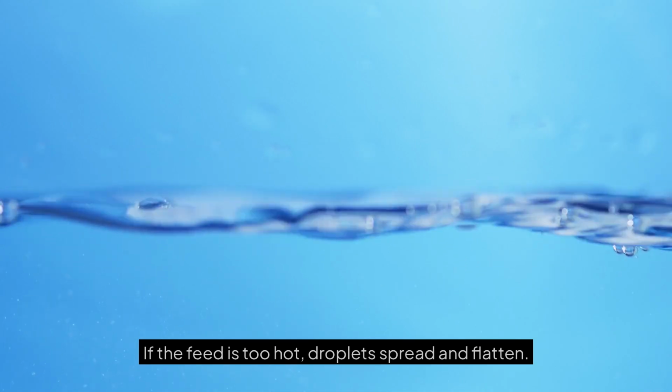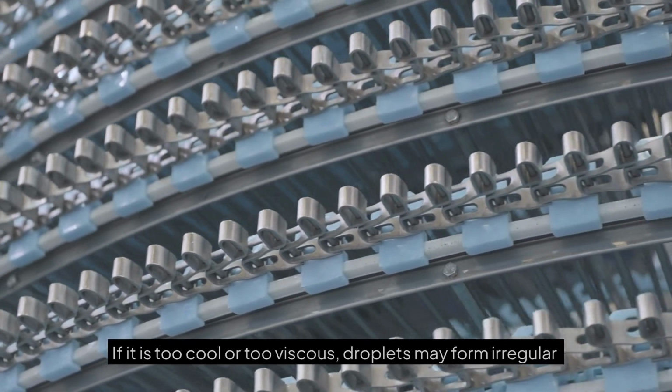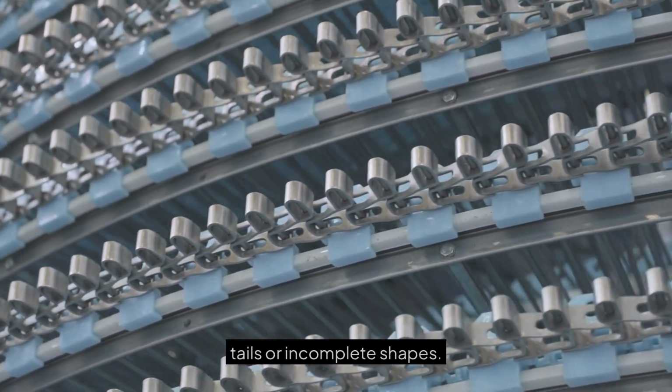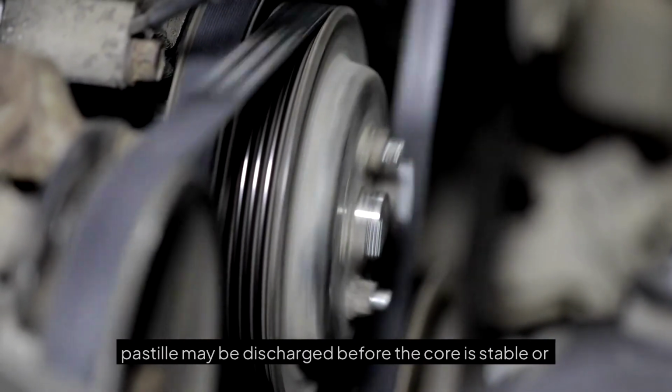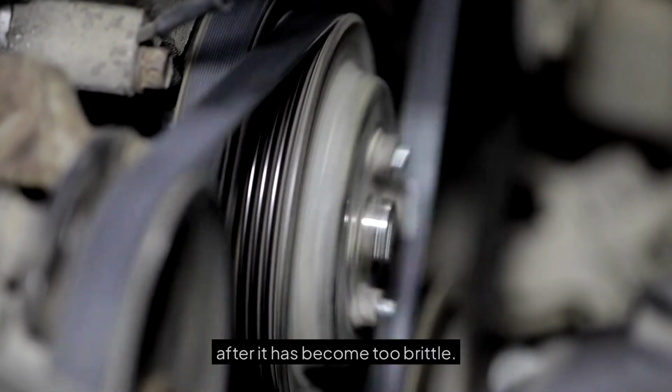If the feed is too hot, droplets spread and flatten. If it is too cool or too viscous, droplets may form irregular tails or incomplete shapes. If belt speed is not aligned with cooling capacity, the pastille may be discharged before the core is stable or after it has become too brittle.